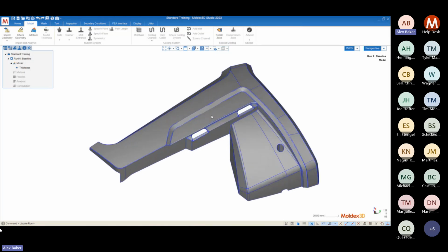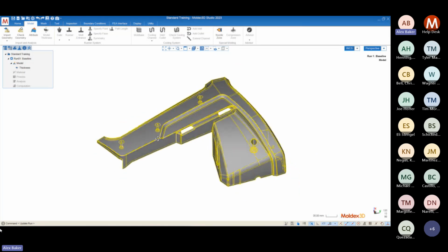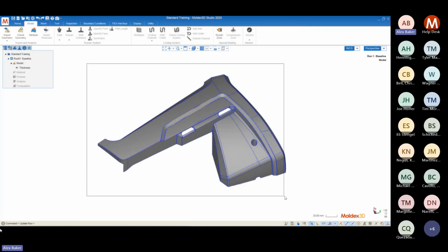Like I mentioned earlier, there is the left click, which just selects your model. But we do actually have a pair of box selections utilizing the left click drag functionality. Left click dragging from left to right will select anything that is completely contained within the box that you create.